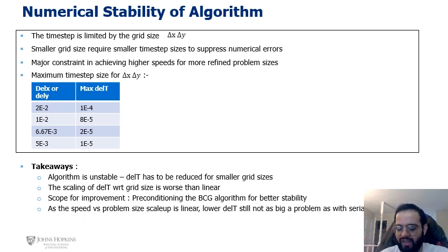However, the size of that time step is also a critical factor, because say we are running 200 time steps with a size of 1e-3 seconds versus 1e-5 seconds, the total simulation time that we actually model varies, and ultimately if we want to model say 10 seconds of simulation time, it impacts, because then we require more number of time steps.